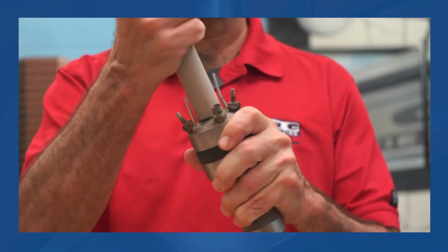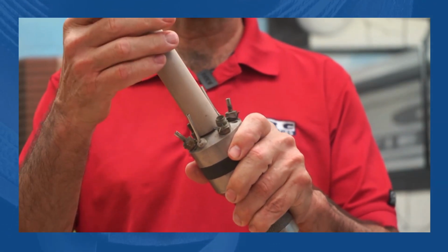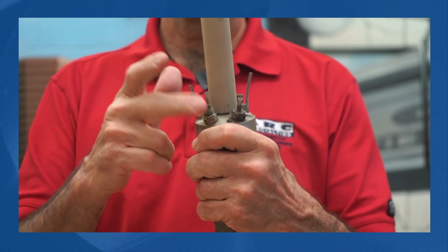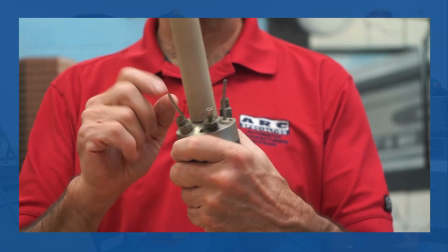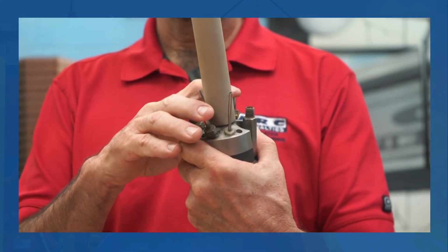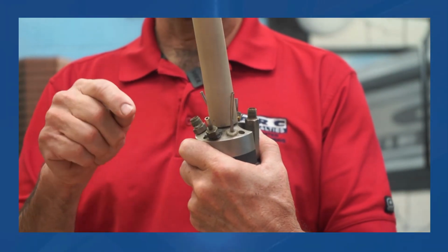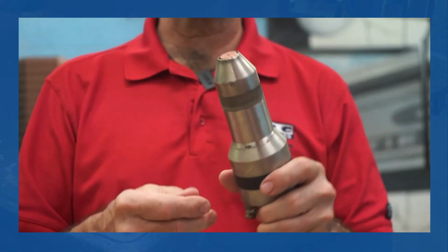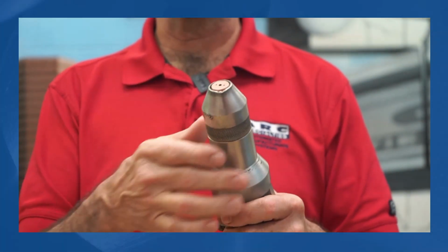This piece is how you adjust the tungsten. You loosen this to loosen the collet. Here you see the two powder ports where the powder flows into the torch. Here is the main arc power supply. Here's the pilot arc power supply. We have 3 different gas flows, and we have water cooling through the whole thing. Very busy torch.